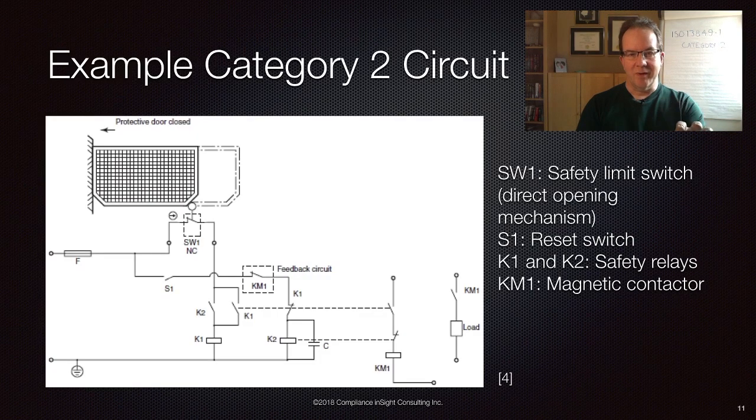So the testing that is present in this circuit is, in my mind, really not adequate at all for a true Category 2 application. And so if you're considering stealing the circuit diagram and using it in your machine design, I highly recommend that you don't do that, because you are likely going to be sadly disappointed in terms of how it actually performs. Okay, so be aware, each of the architectures has some unique benefits and downfalls.